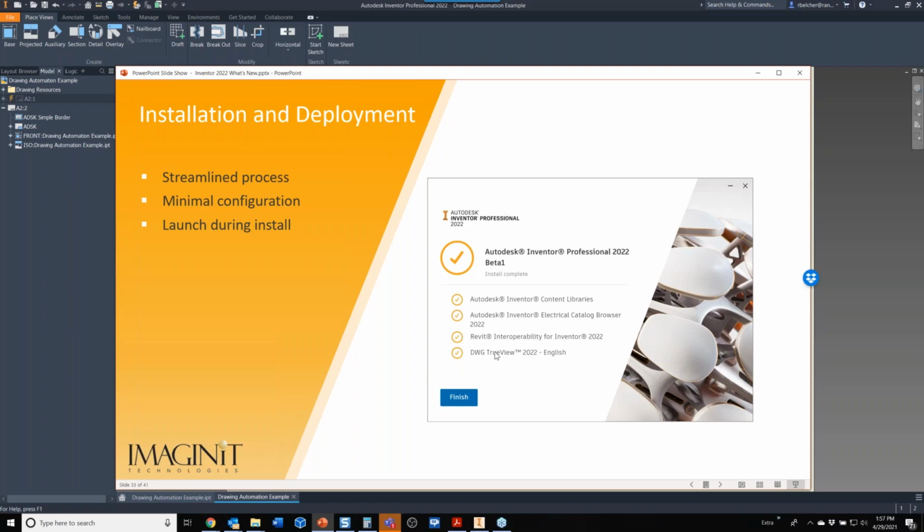You do this online. You go to your Autodesk accounts page. Whatever software you have there or have privileges to there, you can generate your deployments there in a very streamlined little fashion. Choose what versions of Inventor and Vault to plug in and to install. Choose what background files to include. And then when you execute it, it basically creates a bootstrapper file that when you bring it down to your machine, it will build the deployment on your local machine that you can share amongst the users at your facility.